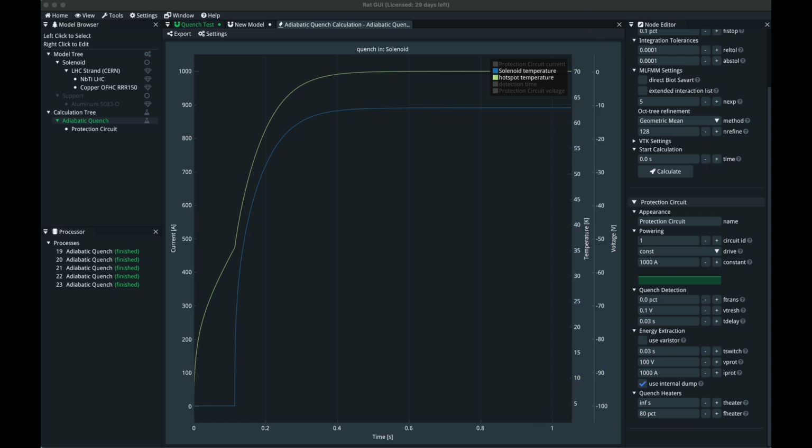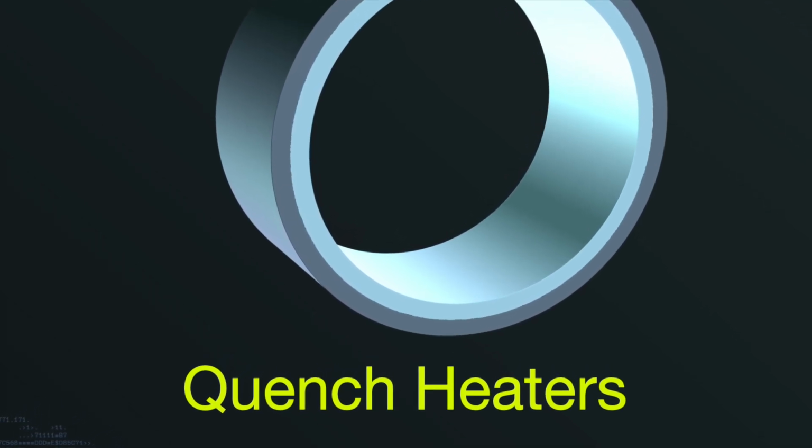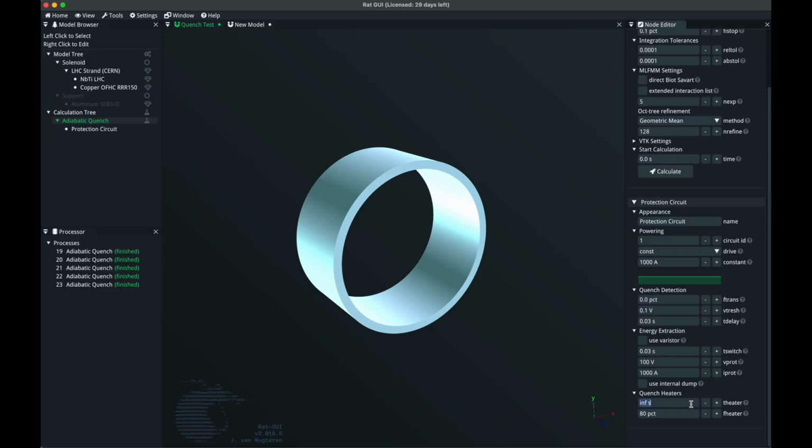That's the next case. Now, another quench protection method is not using energy extraction in any way, but by using heaters. And if you want to use heaters, there is quench heaters here. Basically, what you need to set here is a time at which a certain percentage of your coil has quenched after switching in the heaters. So this is not a heater switch in any way. It is a time at which you know more or less X% of the coil has already quenched.